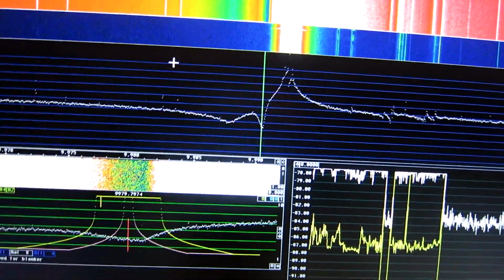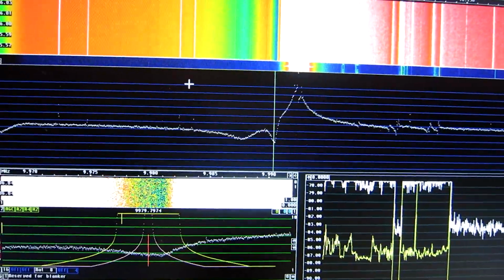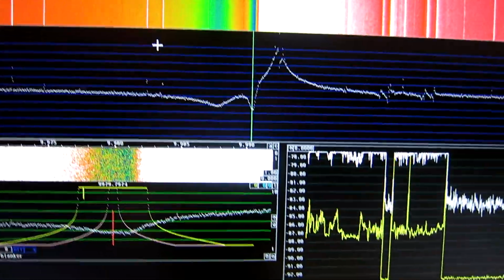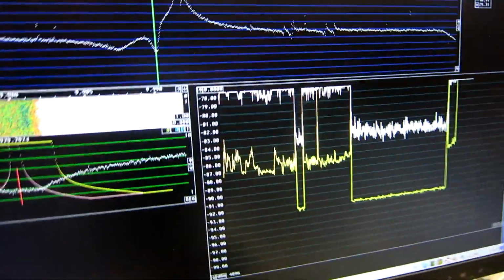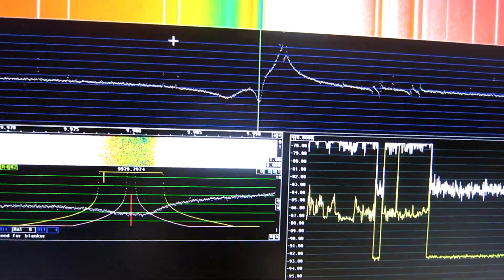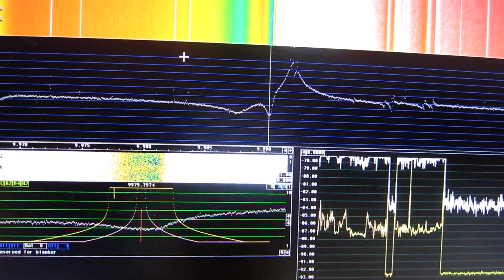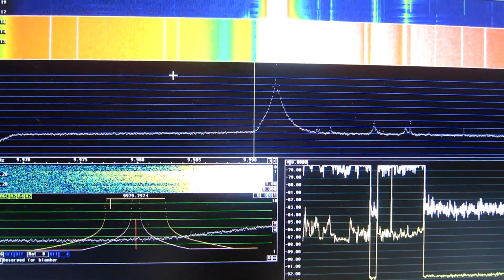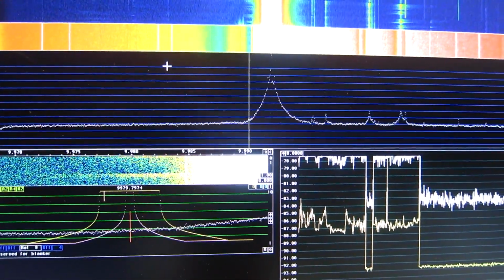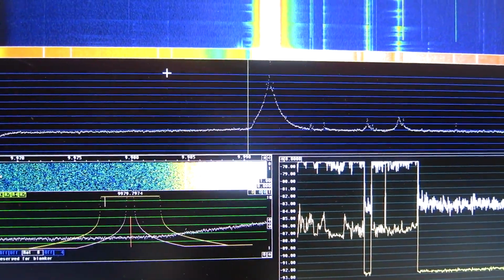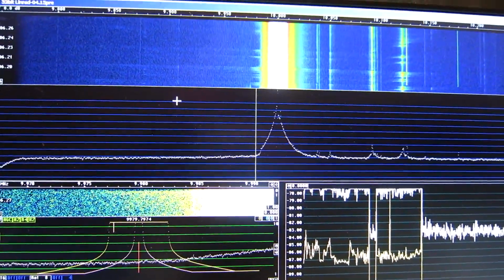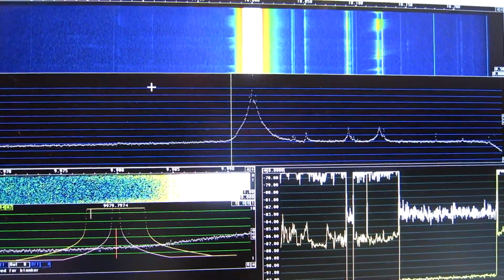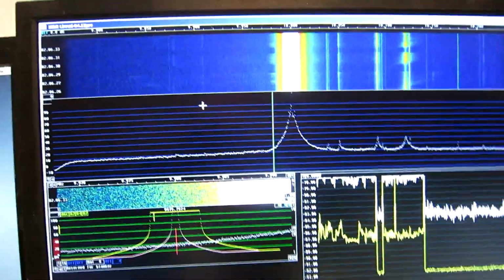With a single section crystal filter, this is what I see. There is a lot of noise from the Hewlett Packard 8657A, but with the 2 section filter it looks like this, and this supports the idea that the noise that I see actually comes from the analyzing tool and not from the amplifier with its crystal filters.